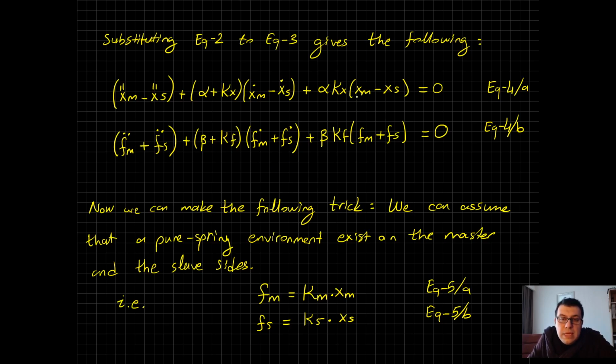So we can assume that the positions of master and slave system, the velocities of master and slave system, the reaction forces on the master and slave systems, and the derivatives of those reaction forces are all being measured from the system. So we can extract this information. These are measured, these two. That is through differentiation. This is acquired by reaction force observers. That's a different kind of measurement or estimation. And these are acquired through proper differentiation.